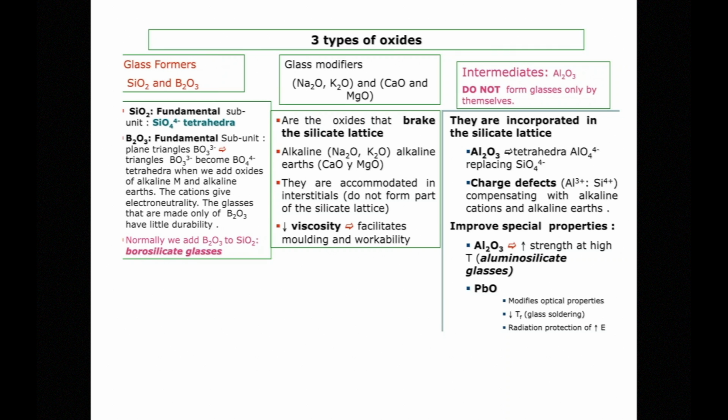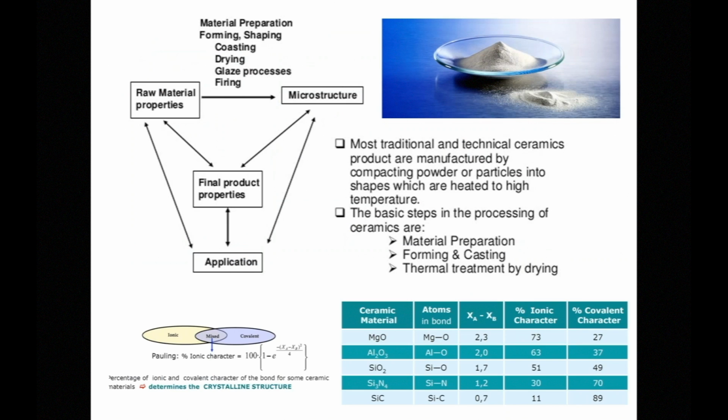So for example, the glass formers are typically your silicate and boron oxide type of lattices. You can modify glass through different sodium, potassium, and magnesium or transition metal oxides. And then the aluminum oxides, which have a tetrahedral arrangement, you can basically dope with different types of aluminum silicate composition. Can be used to modify glass and aluminosilicate properties as well.